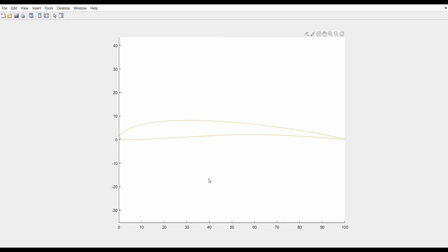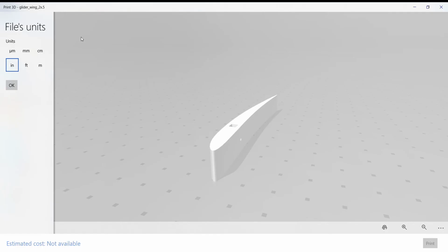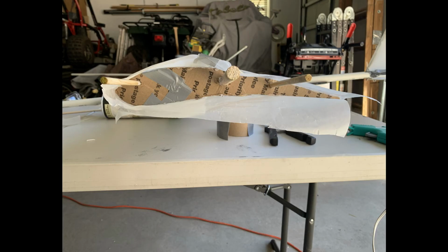And SolidWorks converted it into a SolidWorks sketch. From the sketch, I was able to adjust any lines that were not straight, any corners that were too sharp, etc., and also find a basic geometry so that we can do preliminary calculations. So, after I did that, I created our first iteration of the individual ribs that we were going to use on the first design, and our final design still incorporated the shape of airfoil and our rib design.